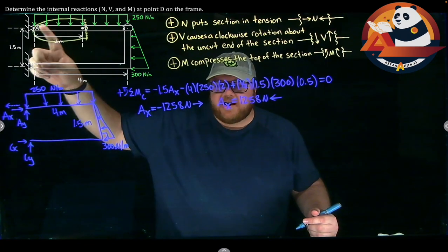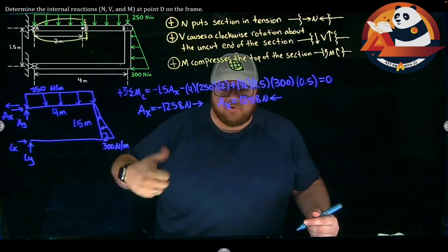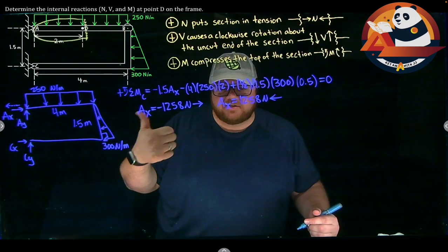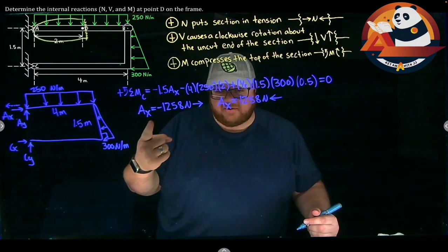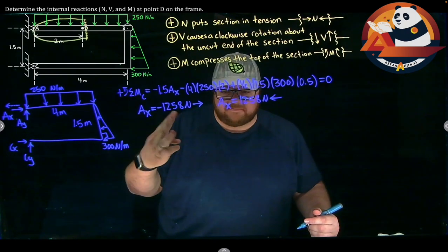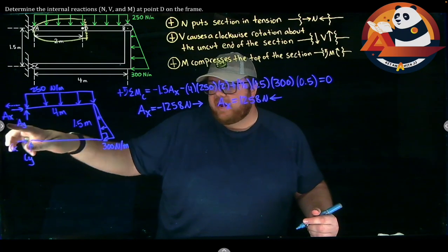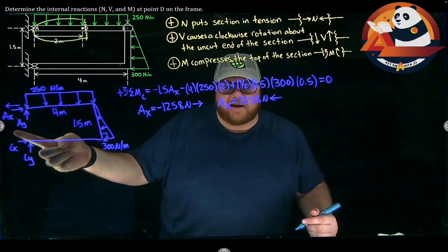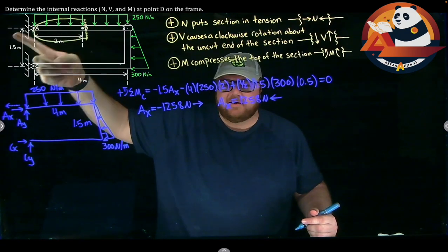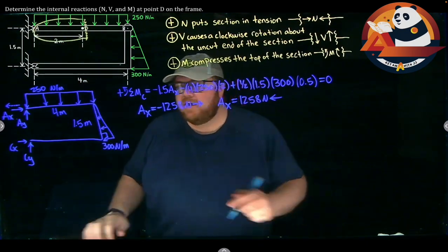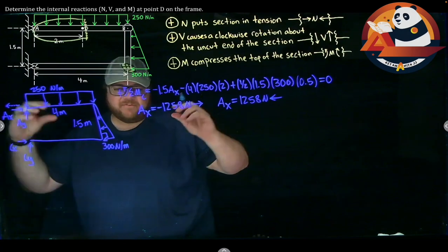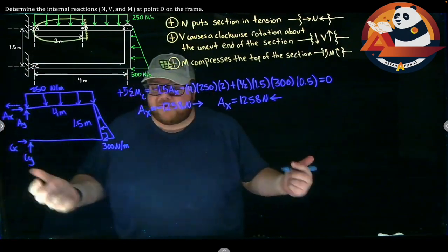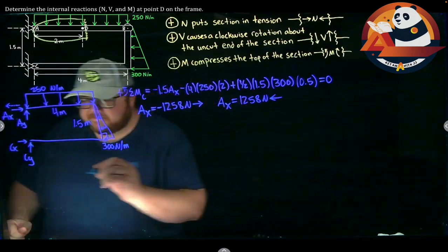So we'll make a new free body diagram. What if I drew just AB? Well, now I know AX. I would have unknowns of AY, BX, and BY. Three unknowns. AX is known, so it's not an unknown for us. But all I need is AY. If I'm circling to the left up here, AX and AY need to be found. If I just sum moments at B on a free body diagram of AB, I'd be able to find AY. So let's just go there.